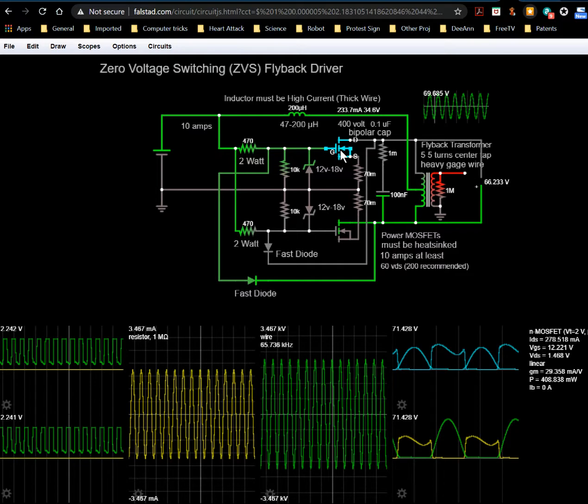And it's as simple as that, but until that capacitance is charged up to some intermediate voltage level, this FET can't really turn on properly. When it's below that, when the capacitor is not charged up, the FET will be off. So at any rate, that has a lot to do with how to turn on a